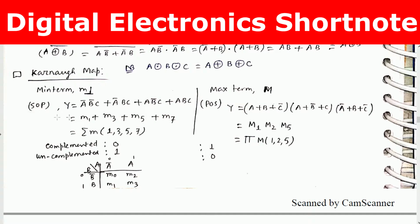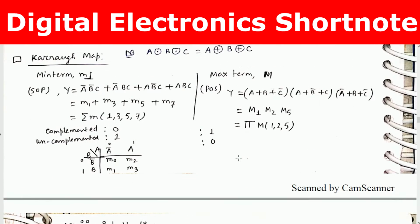So when we are talking about SOP, we take the complemented thing to be 0 and uncomplemented things to be 1. Then you get minterms 1, 3, 5, 7. These are all uncomplemented, so 1 1 1 is 7. But for POS, the thing is just reversed. Complemented things are taken to be 1, and uncomplemented things are taken to be 0. So 1 0 1 means 5. So 1 to 5. Okay, so I have written it explicitly here.